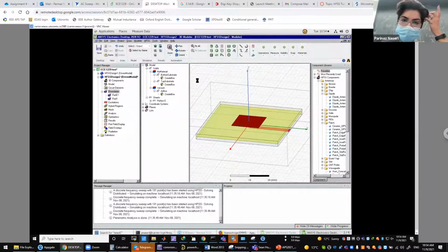Okay, so now this is the radiation. The metallization is okay. My material is okay. Now we have to excite this, right? For excitation, again, I would suggest using a lumped port. You say my input impedance virtually looks like a 50 ohm lumped port. And then where does the excitation go from? If you have a microstrip line here, this is a bit harder, but let's look at it from the side.